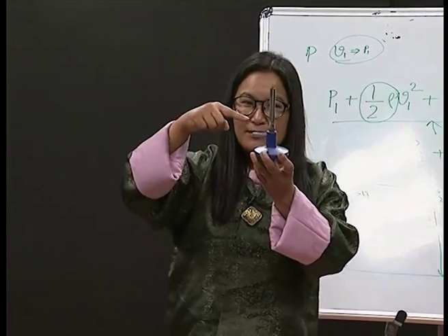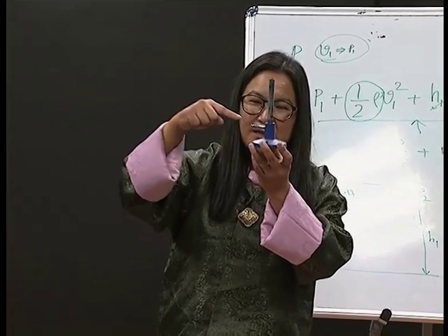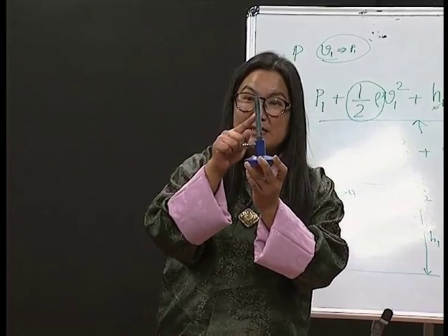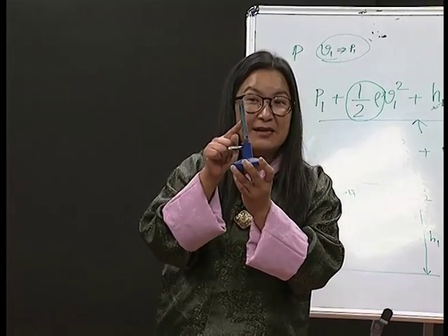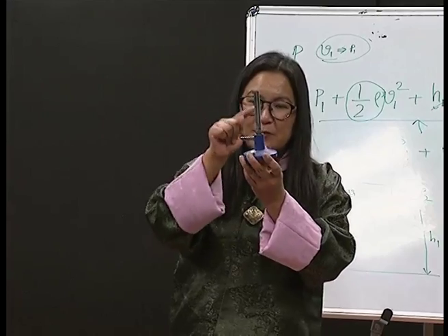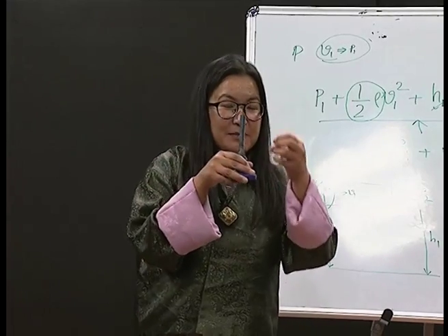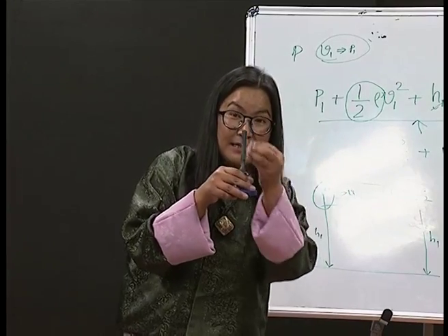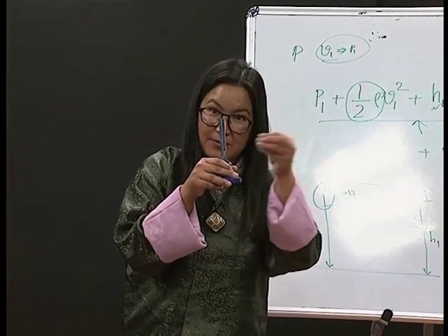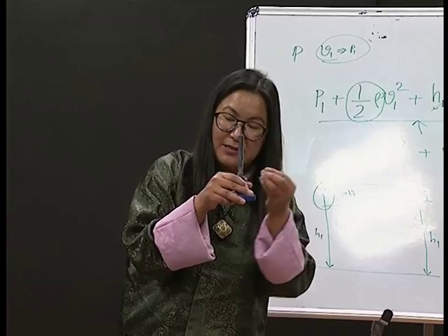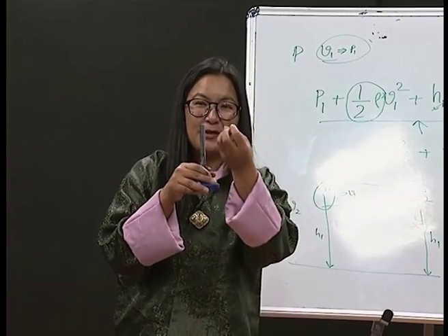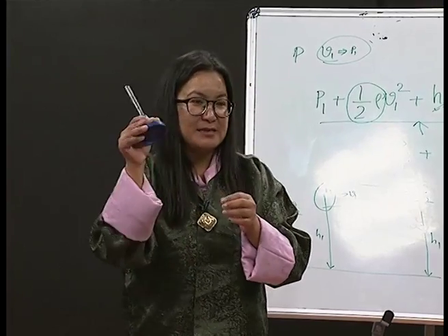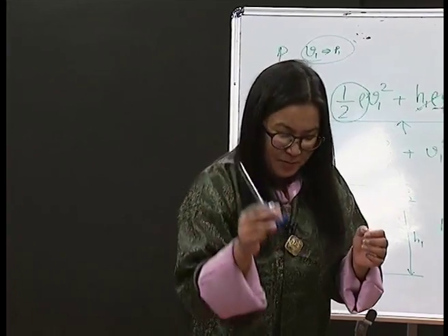So, when this hole is made, and the gas enters here with very high velocity, pressure will be low. Now, outside the pressure is high. So, the outside air will gush in because of high pressure outside and low pressure here. It will get mixed with the gas and then it will burn properly. So, that is a simple application of Bernoulli's principle.